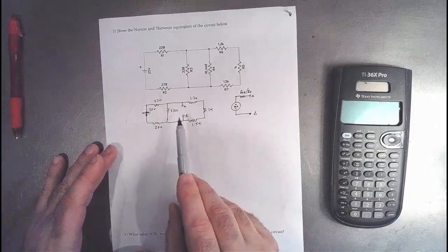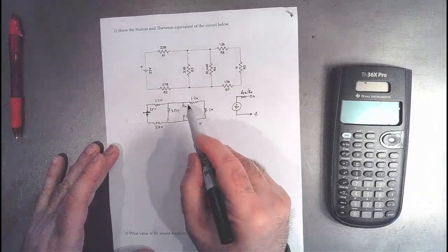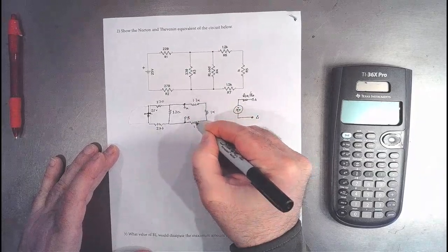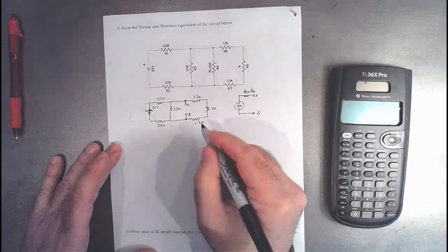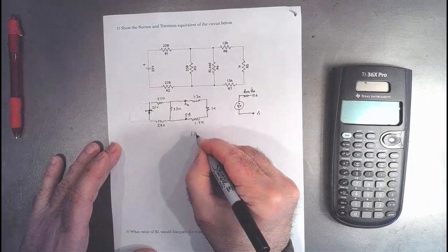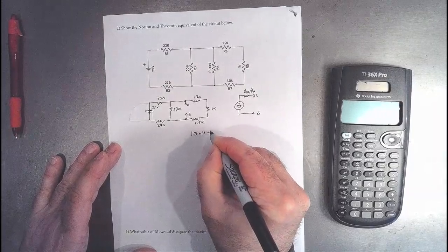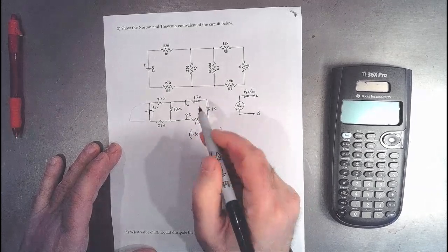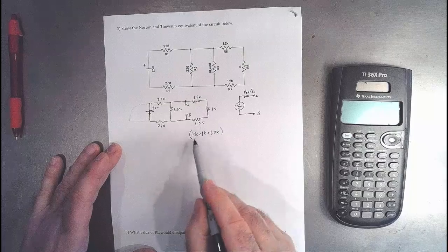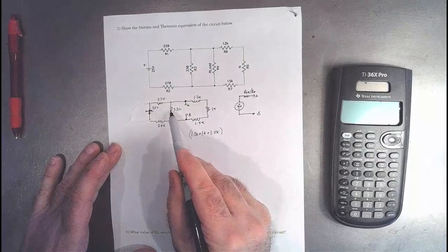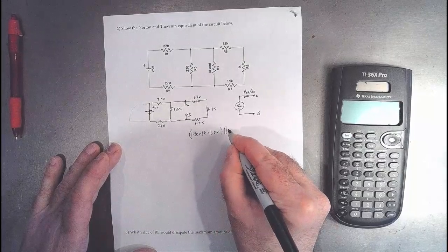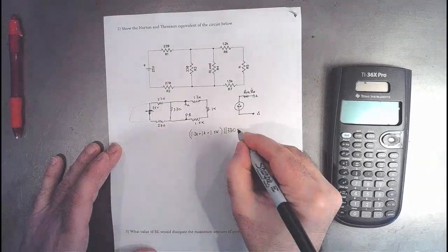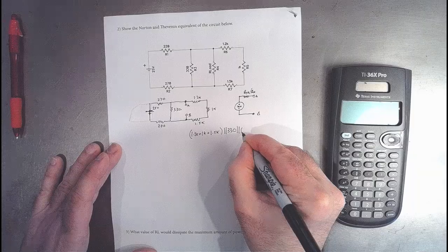All right, so now we're going to break down towards A and B. Well, here's what I see. I notice between this spot and this spot, we've got 3 resistors in series. So that is 1.2K plus 1K plus 1.5K. So that's these guys. And this whole network here is all in parallel with 330 and this branch right here, which is 220 plus 270.